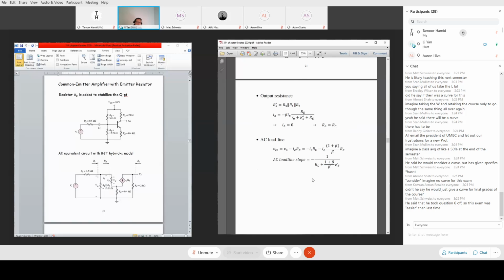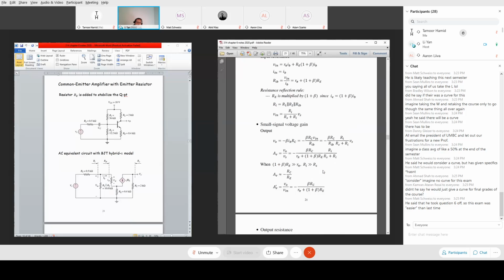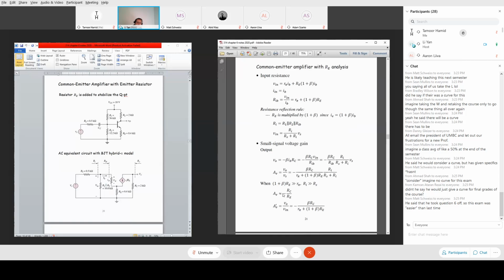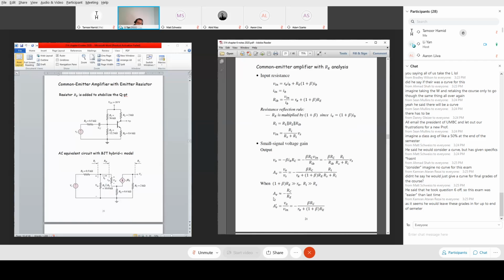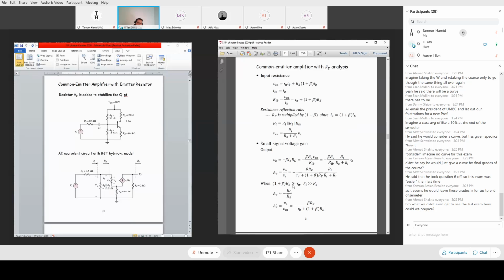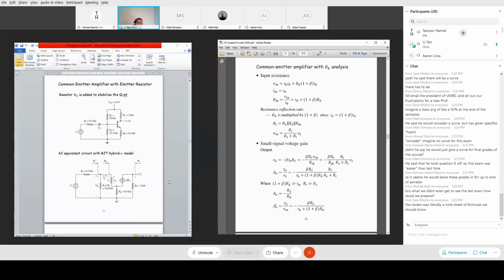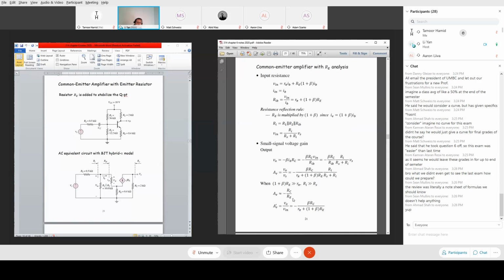Well, here we say we introduce resistance RE to stabilize the quiescent point. And then one benefit is that the small signal voltage gain is simply determined by the ratio of external resistance RC over RE. But if we want the small signal voltage gain to be large, what choice can we make? You can make either RC large or RE small. Generally speaking, we don't want a large RC because it kills much voltage because of Ohm's law. So you may say, I want to reduce RE. On the other hand, when you reduce RE completely, it's as if you remove RE. But once you remove RE, you defeat your purpose. Originally, you add RE to stabilize the DC quiescent point. But that's from the DC consideration. From the AC consideration, you want a small RE. The two requirements seem opposite to each other. How do we solve this conflict?